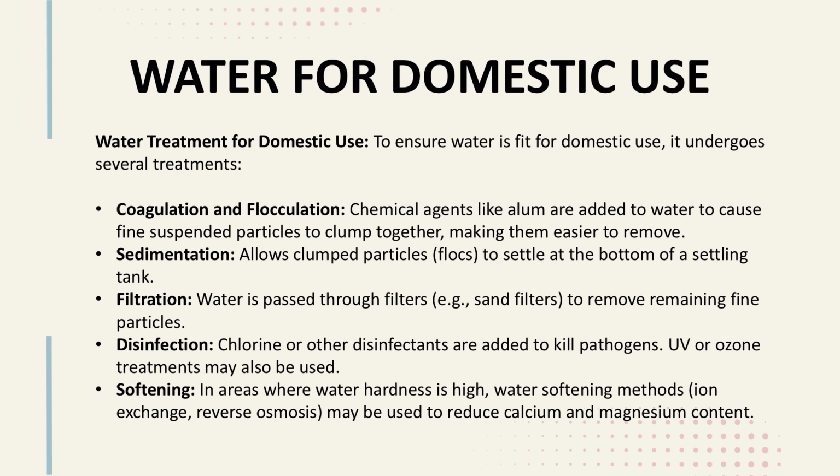Sedimentation. After coagulation, the water is allowed to sit, giving these flocks time to settle at the bottom of the tank. This process clears the water of larger particles. Filtration. After sedimentation, the water passes through filters like sand filters to remove smaller particles that weren't captured earlier. Disinfection. Finally, disinfectants like chlorine are added to kill any remaining pathogens. Other disinfection methods, such as UV or ozone treatments, may also be used.